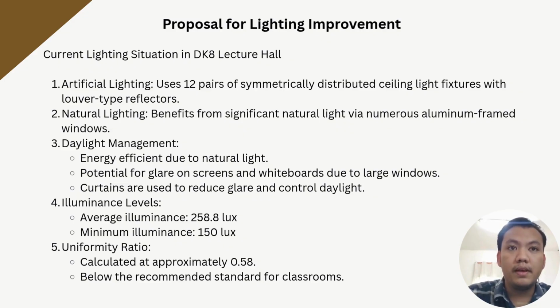The measured average illuminance level is 258.8 lux with a minimum of 150 lux, but the uniformity ratio of approximately 0.58 is below the recommended standard for educational environments, indicating an uneven light distribution.